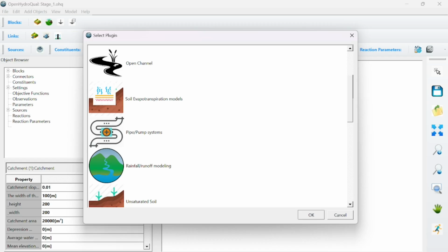And for the case of stormwater control measures, it makes a lot more sense to apply your evapotranspiration to the soil, not to the water ponding. Because the water ponding in a bioretention system is going to be very short-lived, right? It's just going to seep into the ground. And when you have water at the surface on a bioretention, it's usually when it's raining. So your air humidity is actually quite high, so not much evaporation happens during that time anyways. Most of the evapotranspiration happens from the soil later on. So anyways, we use this one.